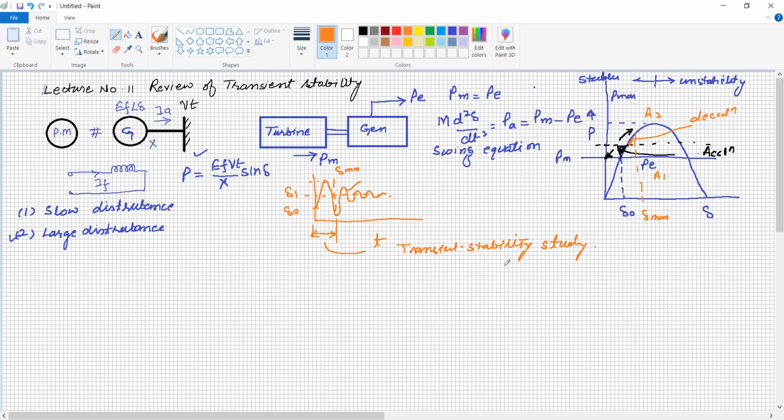So it is quite clear. For transient stability, we are going to consider 1.5 cycle, and after 1.5 cycle the system is going to settle to the new equilibrium position, and the way of tracking to its final value, the brief period during which the system settles to the new equilibrium position, is called dynamic stability. So there are 3 types of stability: one is steady state stability, second is transient stability, and third is dynamic stability.